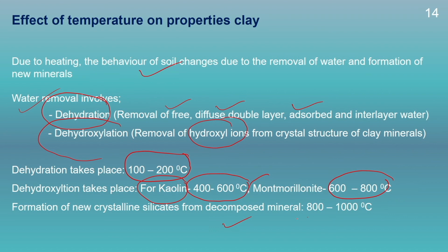So, as the temperature of the clay is gradually increased, the first thermal reaction to occur is dehydration, that is the removal of the free water from between the silicate layers of different clays, and generally this takes place from 100 to 200 degrees centigrade.